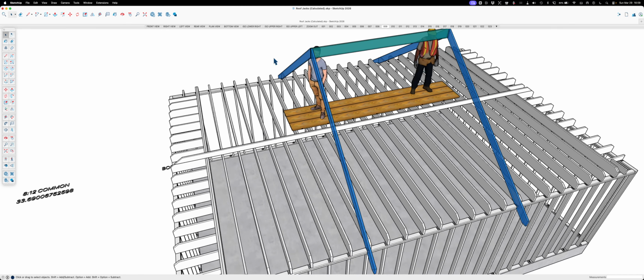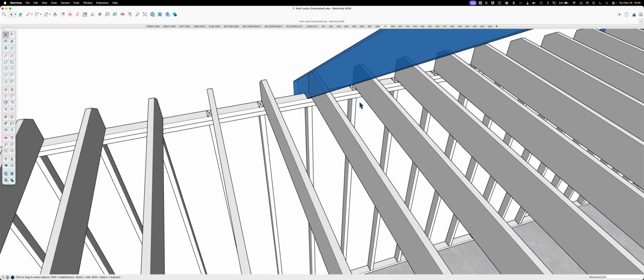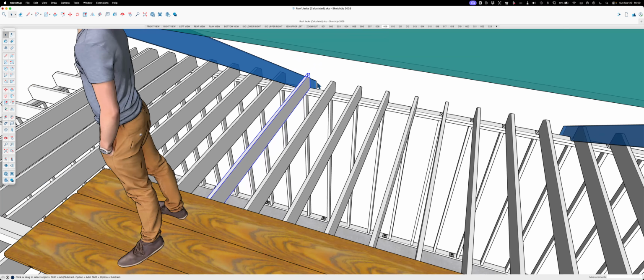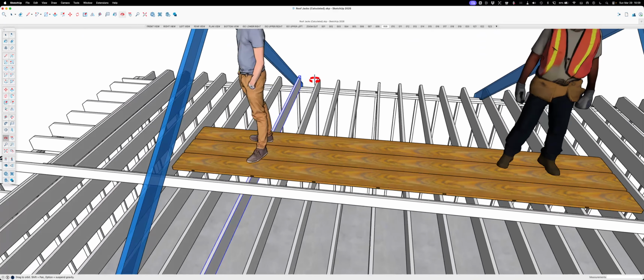And the way to shoot these, it's all spelled out in the code book, was we would do, each joist got 2 down into the plate, and usually it was like 3, because we would go 1, 2 on the same side, a third one on the other side. Then the rafter gets 2 down into the plate, and then we did 2 face nail on this side of the rafter into the joist, and then 2 face nail from the joist back into the rafter this way. So it's like 8 nails per connection.